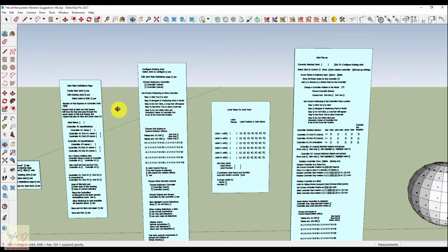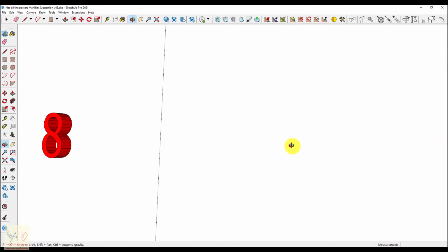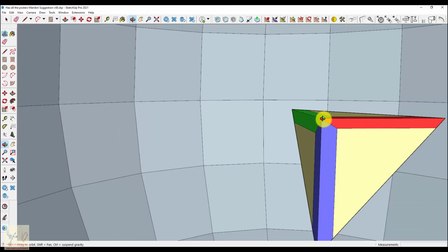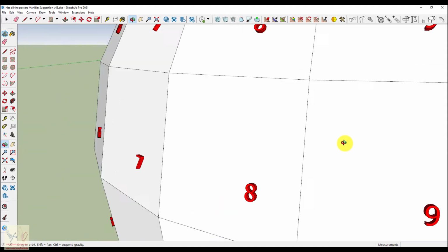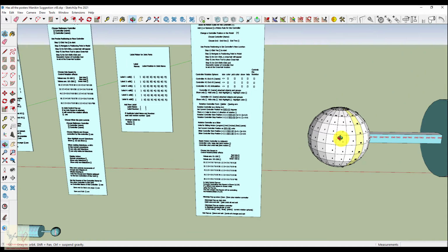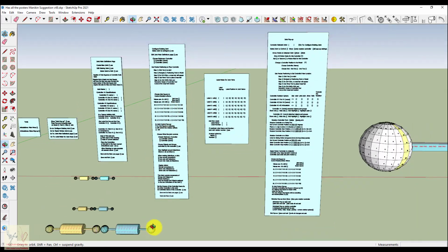And so again, what you're moving around, the crosshairs are basically on that point right there. They are serving as that point. And when you do Control Shift and click, that point is placed on wherever you have put your crosshairs. And that gives you the ability to do precise positioning of your controller ball.